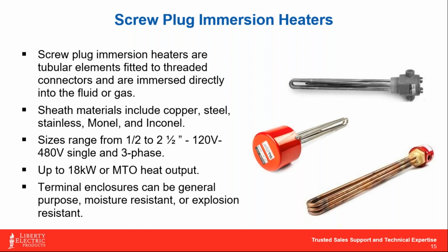You could go find one of those in almost any hardware store, and when you remove the element, you'll notice it's a screw plug immersion heater. These can come in several different sheath materials as well. They go all the way up to about 18 kW, which is a pretty significant heat load. I think that equates to around 52,000 BTUs. So you can get quite a bit of heat out of these.